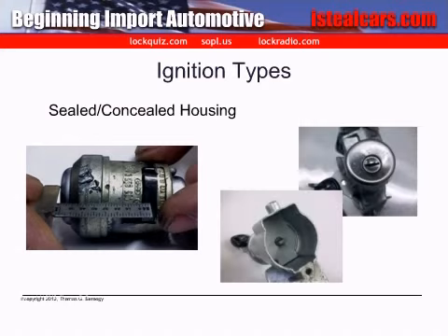Early Mazda, on the other hand, really didn't use a retainer. Instead, the cylinder and other components were installed from the back of the housing. A metal plate was then staked into place, forming a sealed unit. Disassembly of this unit, as we will see later, requires removal of this plate.